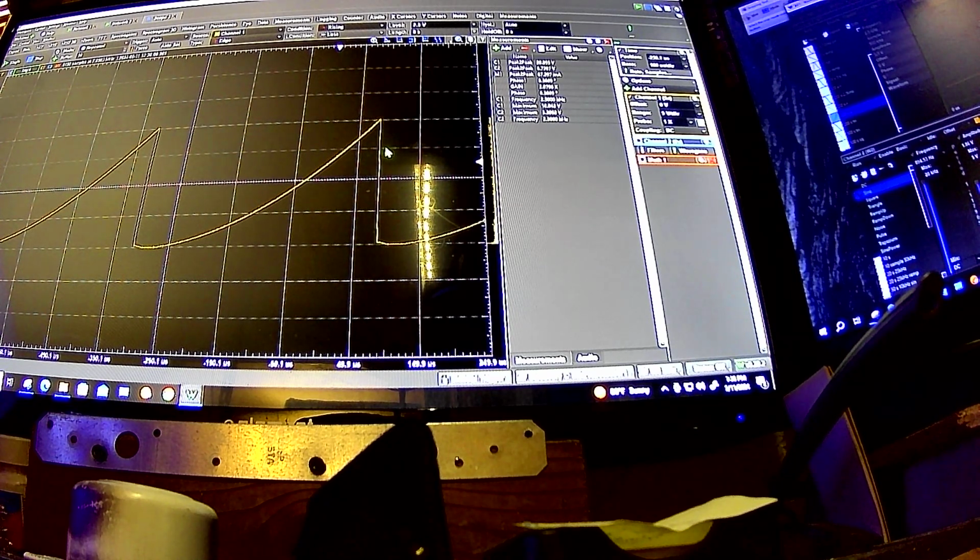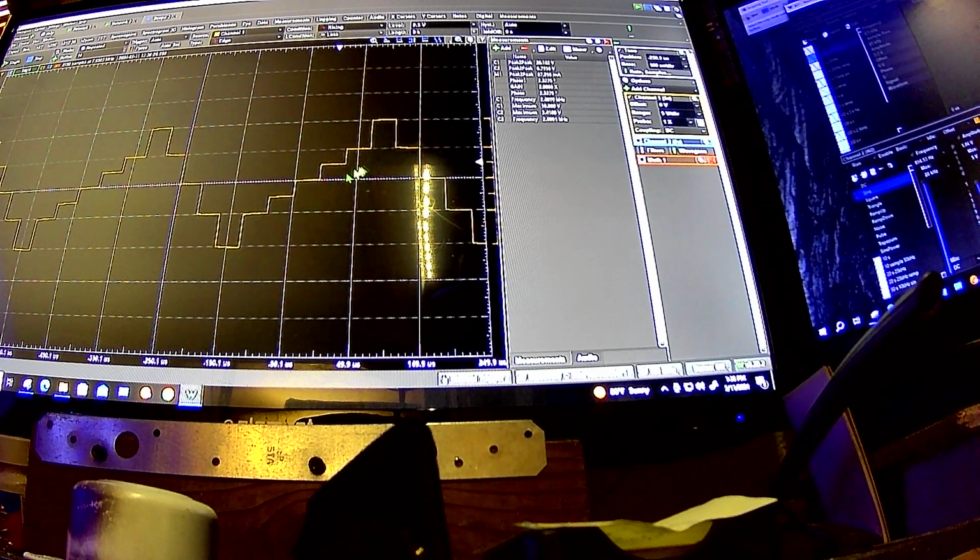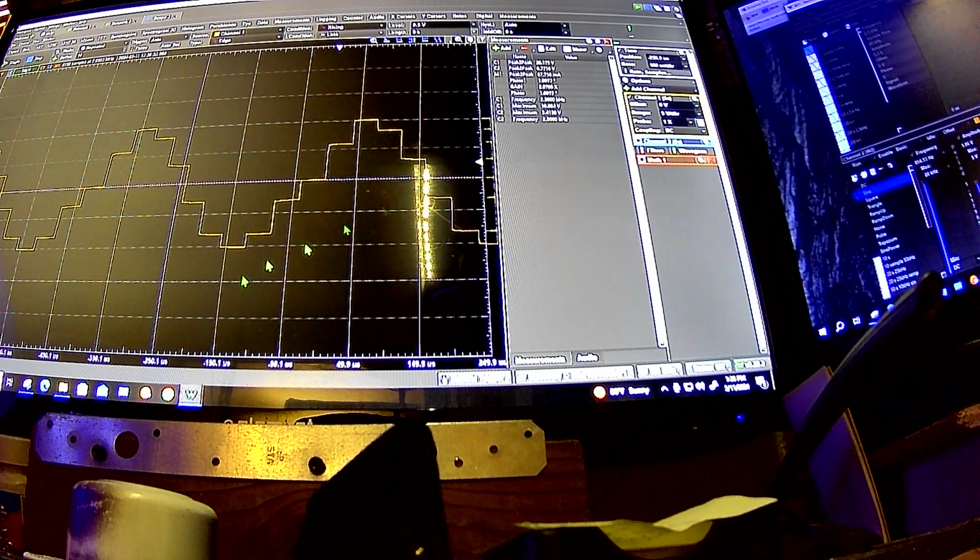Otherwise, sound cards and so forth do use filters. They're usually not digital, because digital filters aren't going to do you any good there. This is a physical effect, more about the process of electronics. There's no computer code you can write that's going to turn this into a sine wave, or anything resembling a sine wave. So you've got to use actual electronic filtering for it.